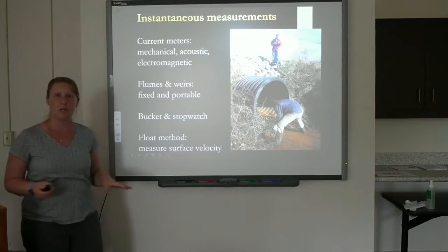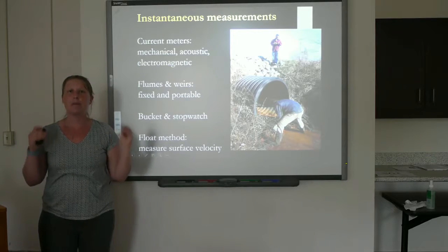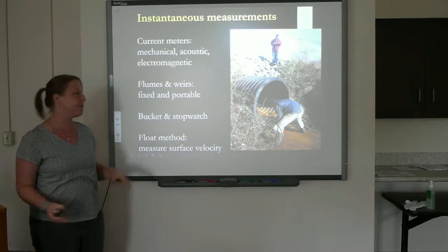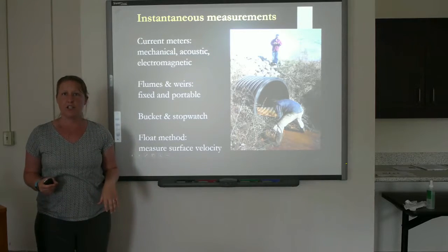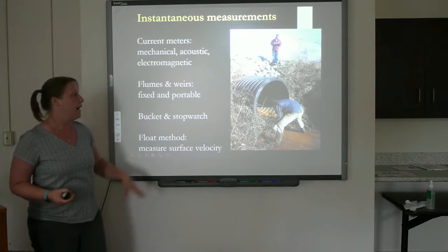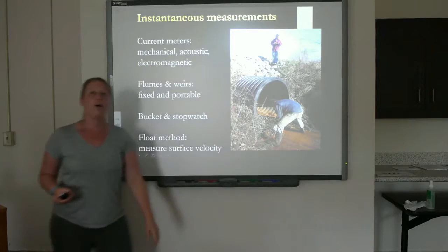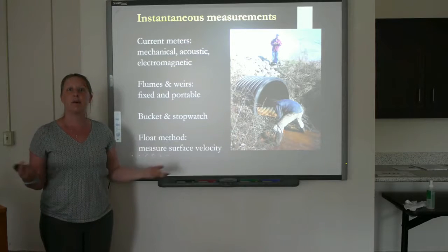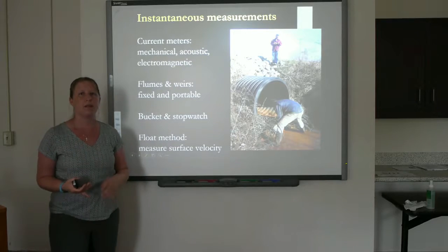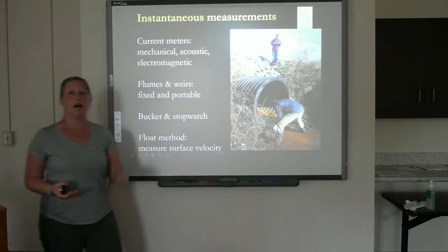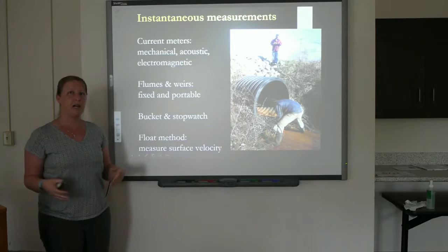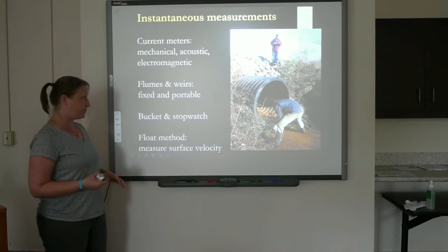The only method that we use that's truly measuring the actual flow rate, truly measuring the volume of water per time, is bucket and stopwatch. And that's exactly what it sounds like. It's what he's doing in the photo, where you see how much time it takes to fill a bucket with water. We'll use this where there's a pipe or a culvert, some discharge where we can put a bucket under it. And we'll average 5 readings usually to get a good measurement.